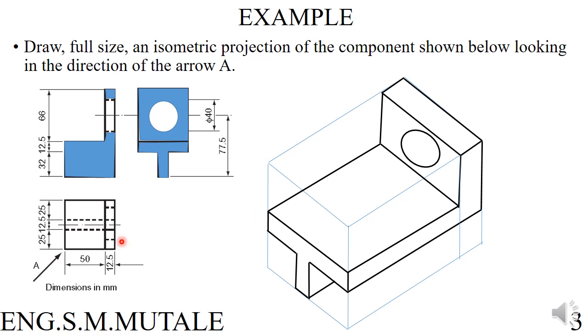Okay, and then when you view from your plan, which is this one, these dotted lines are representing this portion which is going all the way there. There's one there and there's another one going all the way, which you can see. So when you view from the plan, there will be two lines going all the way like that, but you can't see them. They are passing down, they are connecting to this top. Okay, and then these two dots which are there, this thing, as I said, it's going all the way, it's reaching there. And then these dotted lines you're seeing here, they are for the circle, because when you view from up there, this is a through circle. It's there, but you can't see it. So this is a 3D which will be produced.